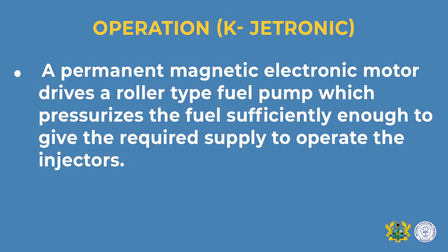In this arrangement, there is a permanent magnet electric motor which drives the roller type of fuel pump. And this pump pressurizes the fuel sufficiently enough to give the required quantity of fuel supply to the engine according to the speed and the load demands.